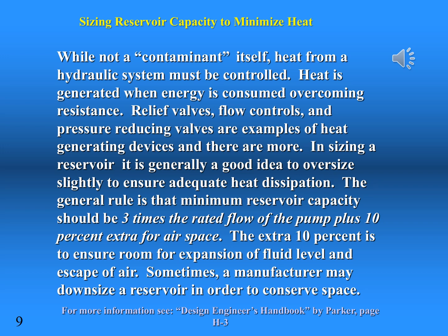The most important job of the reservoir is to shed more heat than what can build up, otherwise the system may overheat. To a large degree, the hydraulic machine's ability to manage its heat is determined by its fluid capacity. The starting point is sizing the tank to at least 3 times the rated flow of the pump.